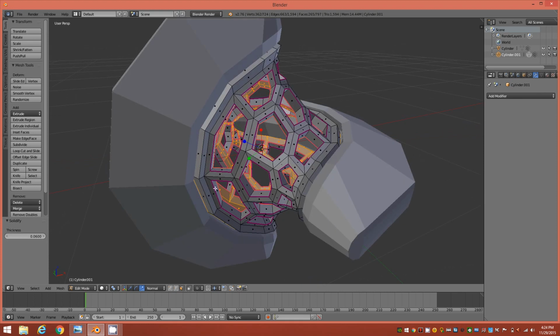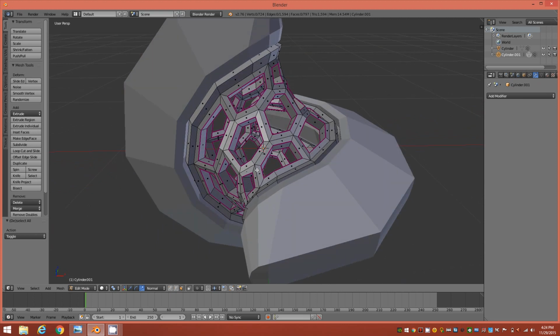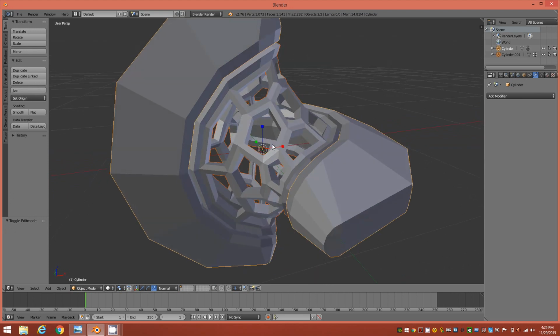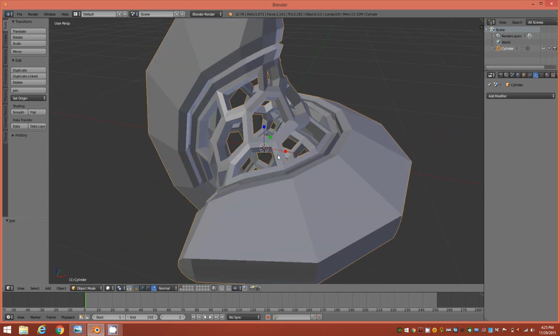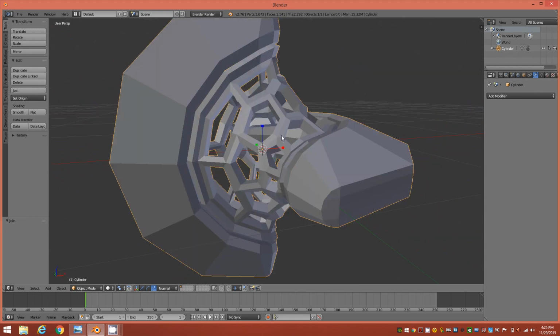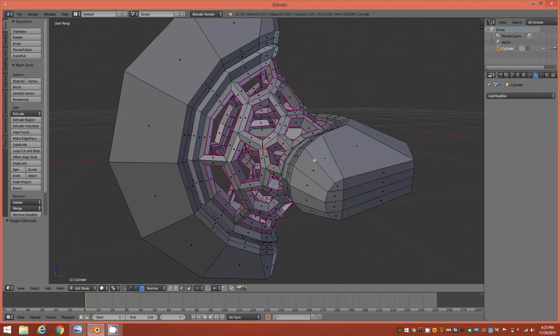So then we could deselect everything, and we're going to attach these two parts now. All right, so we're going to tab out to object mode, and we're going to hold down Shift while we select the other object. All right, so now both objects are selected, and Control J to join. And now they're all one object. Okay, although they're still separate sub-objects or sub-elements. They're all in one object, so we can tab back in and edit on both parts now.